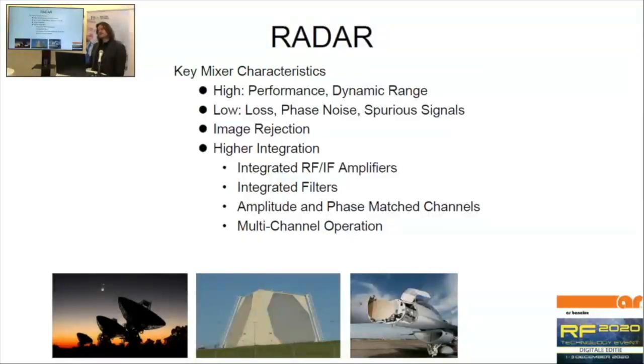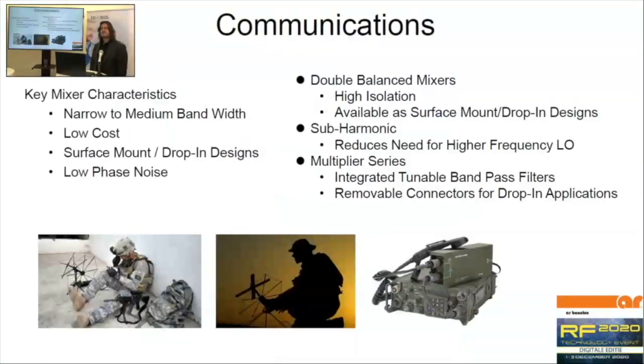Do we want filters in it, depending on the bandwidth, depending on the frequency used? And sometimes amplitude and phase matched channels should be there as well. But that also means that your mixer should be phase matched. So those are questions to ask yourself and then narrow down the ones you can use.